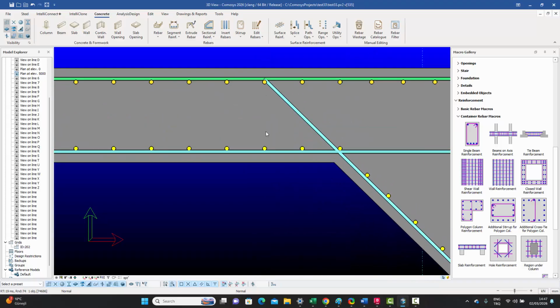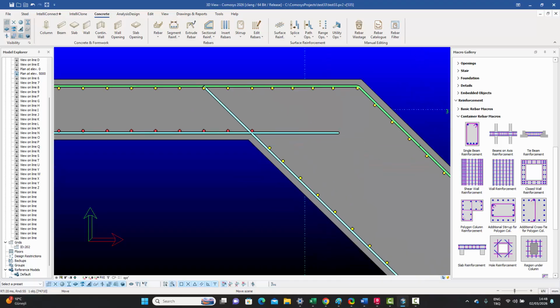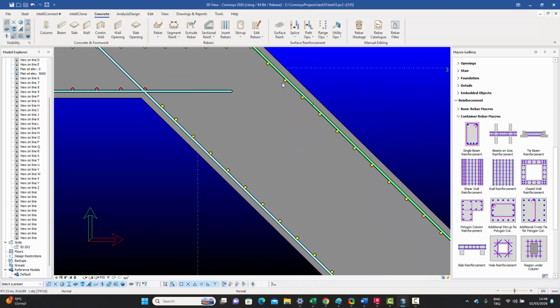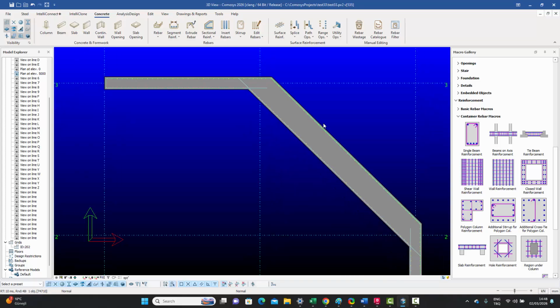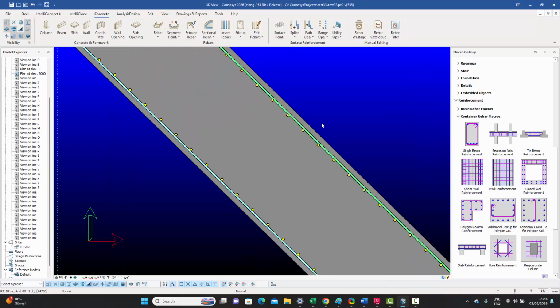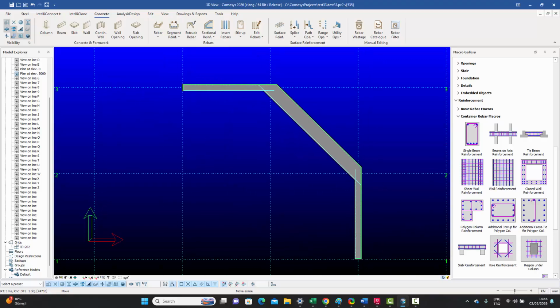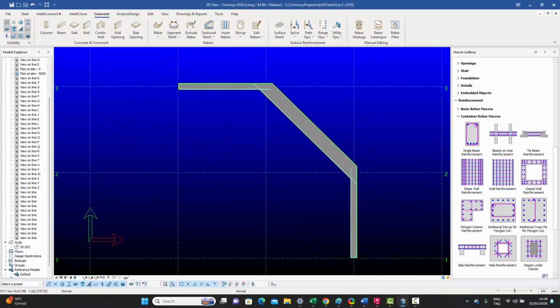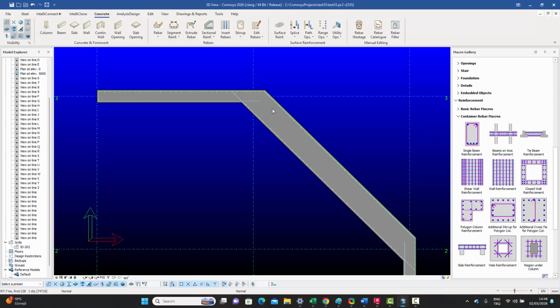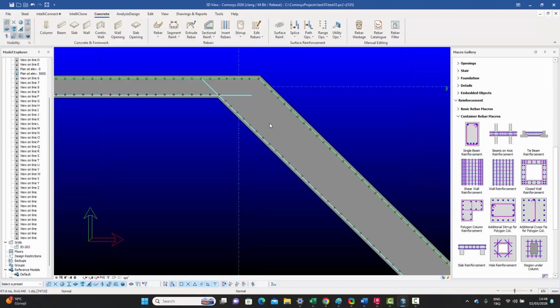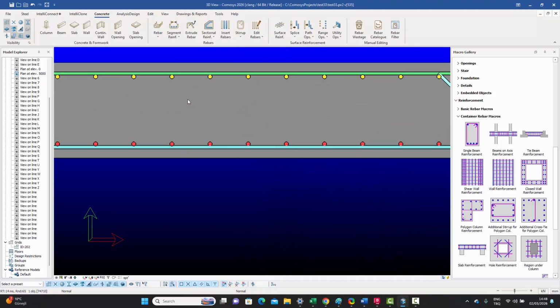this one is now perfectly aligned with this one. This one is perfectly aligned with that. That one is perfectly aligned with that. And then that's continuing. But on this side also, this one is now perfectly aligned with this one. This one is perfectly aligned with this one. So it's a lot easier for us now to put the cross ties. Actually, what we could have done was we could have chosen a thinner wall. It would have been easier to see. I made this a bit too thick, but we get the idea over here. See, they're perfectly aligned over here, as you can see.